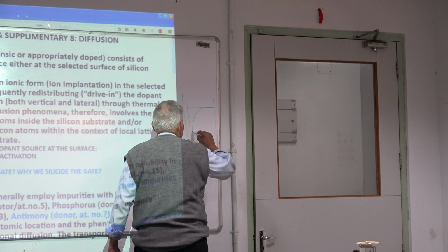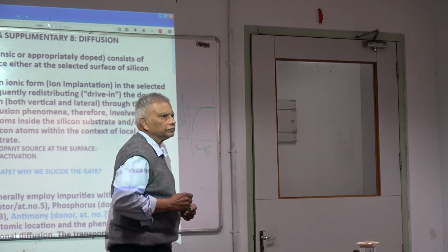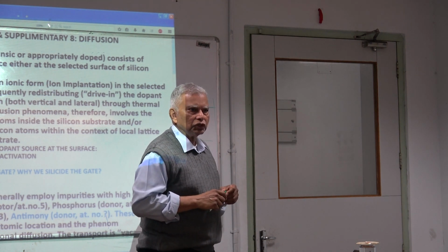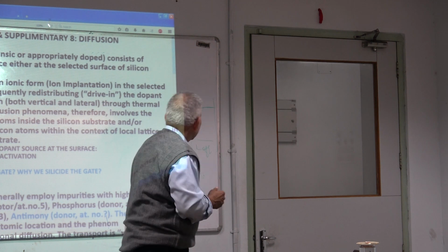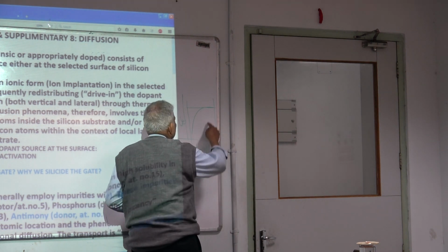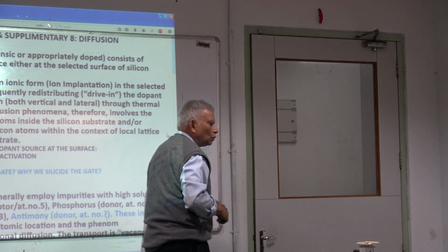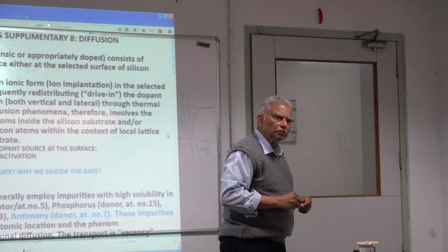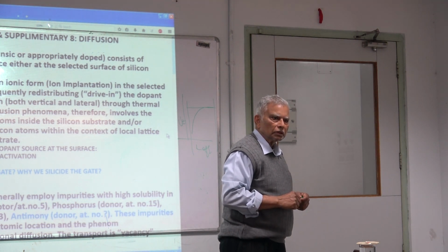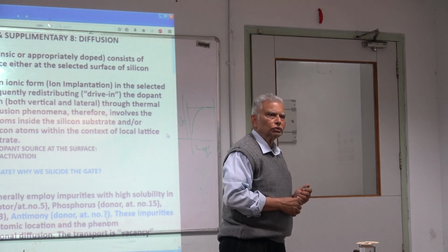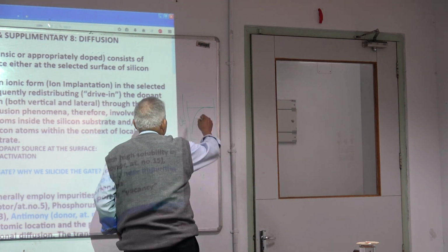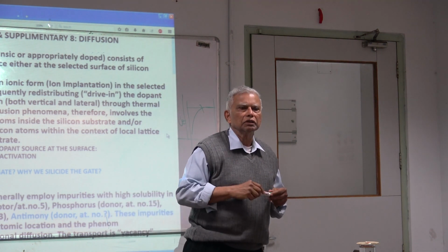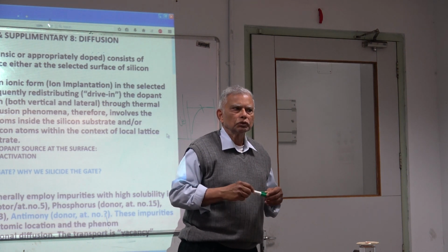So, what is the reality? In reality, any technology does this. What does that tell you? Any generation of technology has threshold versus channel length affected. Why? Because the type of device we built is a surface device, and two things matter: short channel effect and threshold modulation by DIBL. Those two phenomena you should really understand hard.